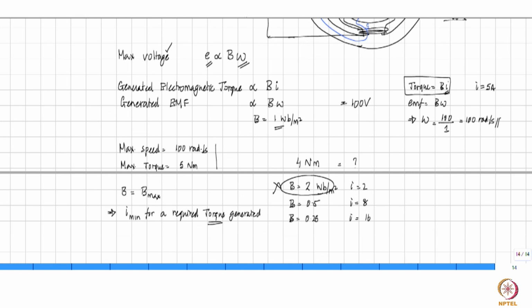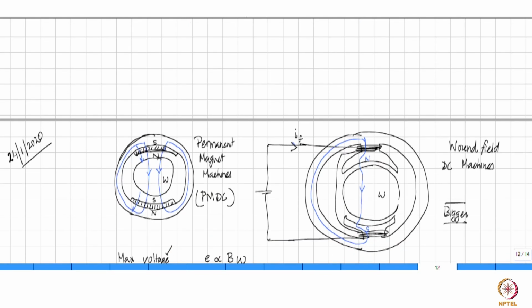Yes. So, there are different restrictions to the level of magnetic field. One is, what is the maximum current that this conductor can take? That is one restriction. Second is, that magnetic field has to flow through this arrangement of the stator, and it has to be flowing through all these regions, everywhere, right? So, if that field has to go through all those regions, you don't want iron to go deep into saturation.